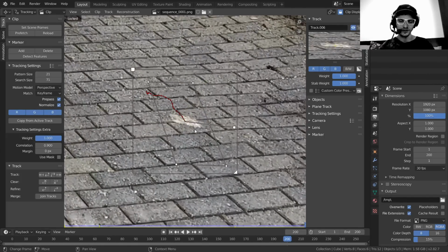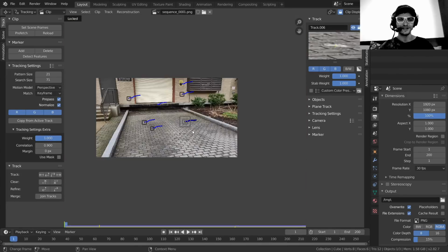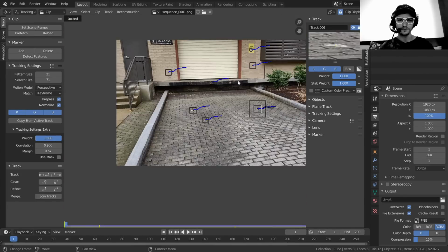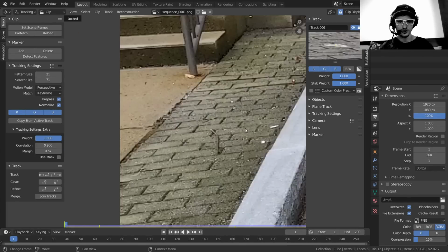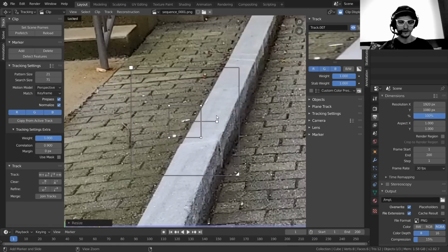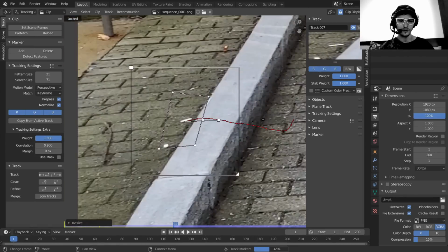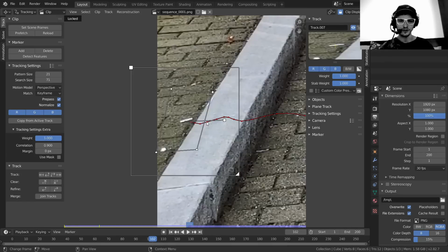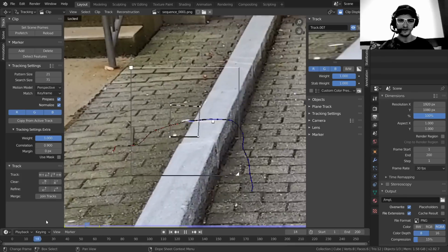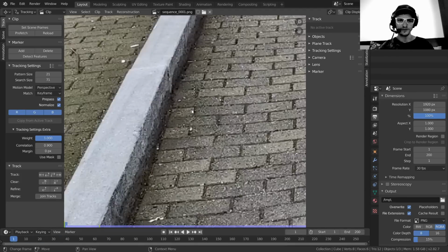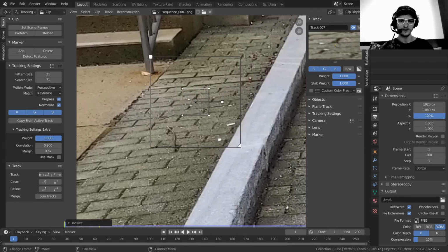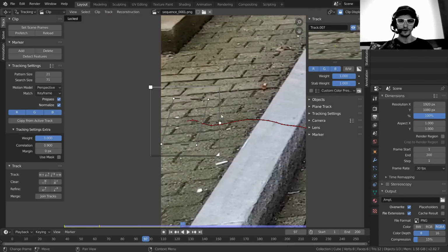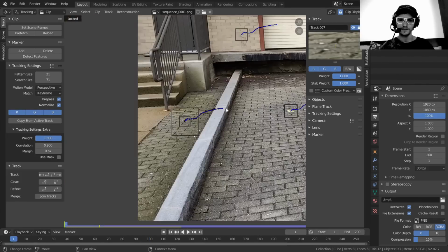So really I'm just hitting Control T a bunch of times until it makes it to the end of the shot. So we have a bunch here. It'd be nice to get some on the right or the left or the foreground. Let's try the left. I'm seeing a good tracker over here, although I have a feeling it's going to go off frame. Oh, by the way, there's some heavy perspective distortion because this curb thing is much higher than the floor. So let me not use that. Instead, we can sample only from the floor, although that should go off frame pretty quickly. But we can lock it anyways.